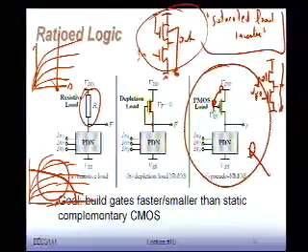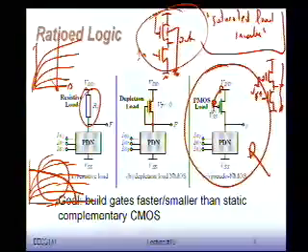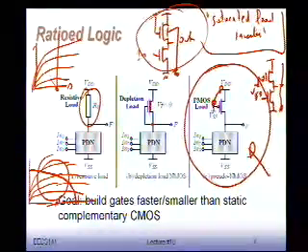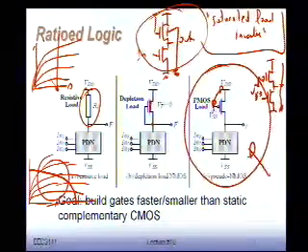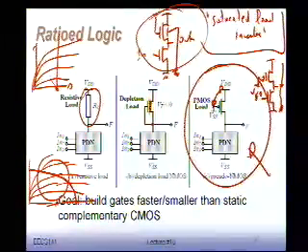Good. So the idea is that suppose I have to build a 10 input gate. In a CMOS gate, 10 inputs would be 20 transistors. Here I need only 11 transistors: 10 in the pull-down network, 1 in the load device. So it's a simpler gate, and potentially you can make it faster because of this logical effort type of thing I was talking about. So fast and simple, which is quite nice. But as I said, you pay some penalties in noise margin if you're not careful.